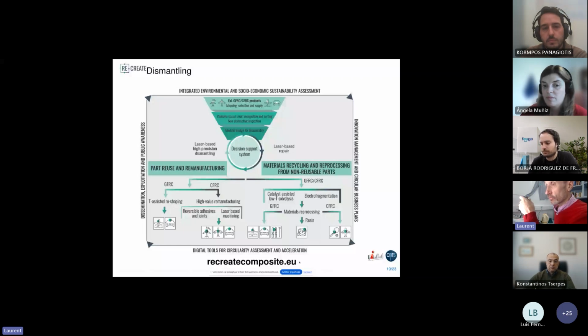We need very good laser beam quality, so we use diffractive optical elements to ensure spatial top hat lasers on the surfaces. We also need to protect the coating of the surfaces from plasma thermal effects and use additional coatings.